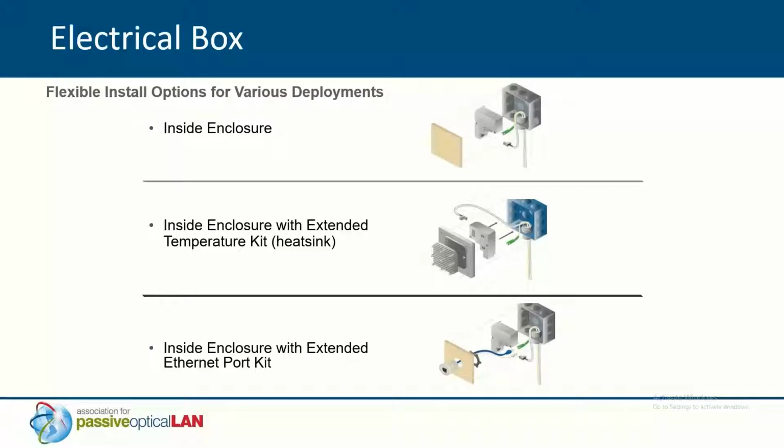You can run, for instance, a hybrid cable that provides a single mode fiber for data connectivity and the copper pair to power the ONT, and run that 20 kilometers plus per the GPON spec and the next gen PON spec, and basically provide Wi-Fi capability or a camera out in the middle of nowhere. So, some new stuff coming.